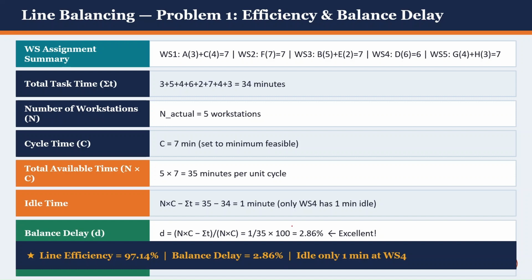So the line is completely efficient. The line is very efficient. We have a balance delay of only around 2% or 3%, so the line is 97% efficient. This is how the calculations have been done.